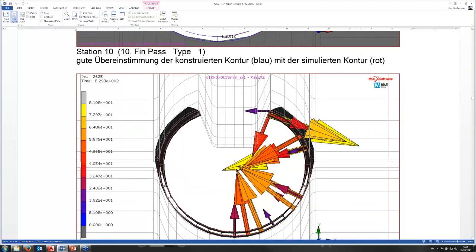As you can imagine, because our shape isn't quite round as it enters the fin pass, we see high forces acting upon the strip edge itself, the fin, to help it form the sides of the tube, which are essentially flat. In doing so, this can damage a strip edge. High forces at strip edge at this point can lead to ripple, elongation. In other words, the material's grown in length compared to that of the base. This could give us a weak weld, a rippled weld, an intermittent weld. So all negative effects.